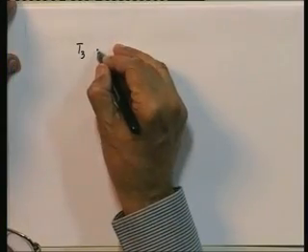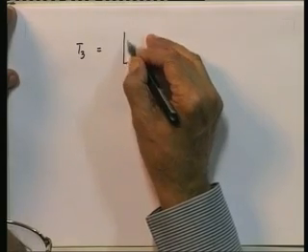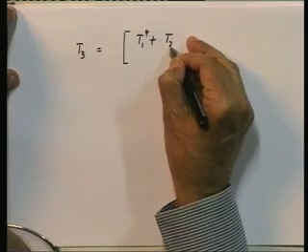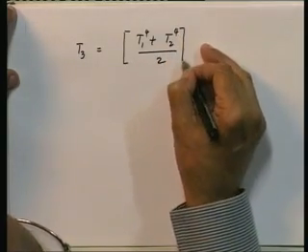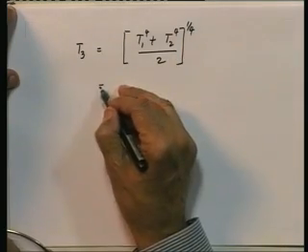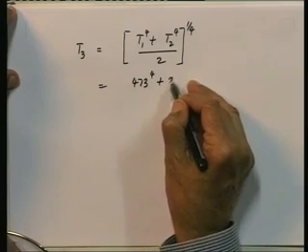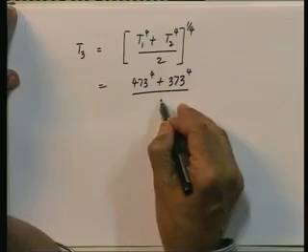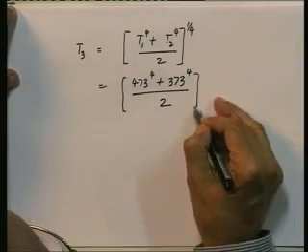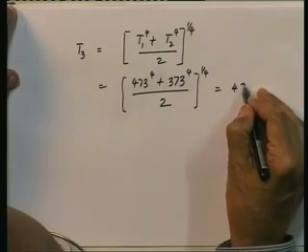The rate at which you extract heat at the surface 2 is 1803 watts, and that is what maintains the steady state in that enclosure. And further, if you calculate T3 in this case, again making use of the fact that A1 is equal to A2, T3 becomes T1 to the power 4 plus T2 to the power 4 divided by 2, the whole thing to the power of 1/4. So, it is nothing but 473 to the power 4 plus 373 to the power of 4 divided by 2, the whole thing to the 1/4, which is equal to 432 Kelvin.